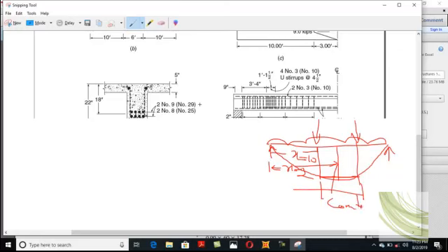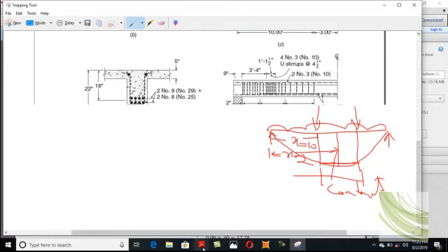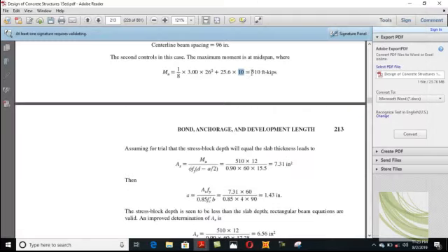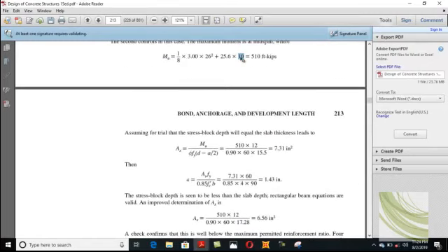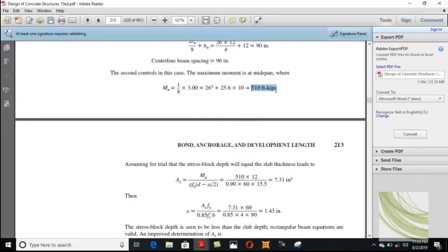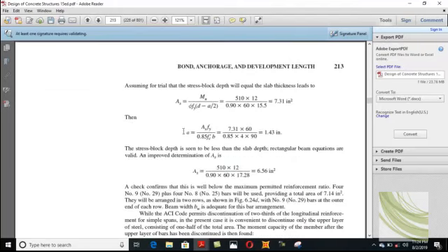They assume that the bending moment between these two points is constant. Clear? So you need not be confused at 13 and 10. That gives you the same result. Clear? Now the maximum moment is achieved. Now you will calculate the AS. So you know Mu divided by phi.